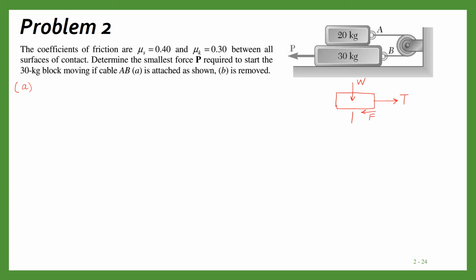Now according to equilibrium, W will be equal to N, which will be equal to 20 into 9.81, which will be equal to 196.2 Newton. Okay,